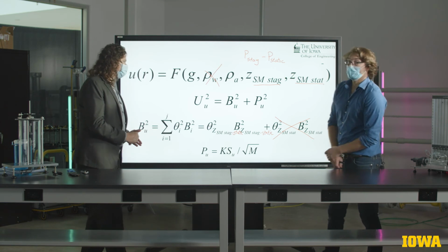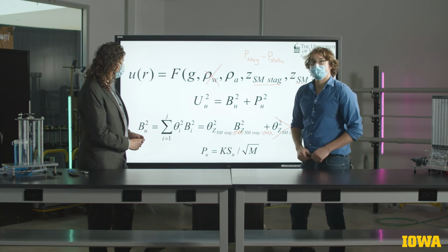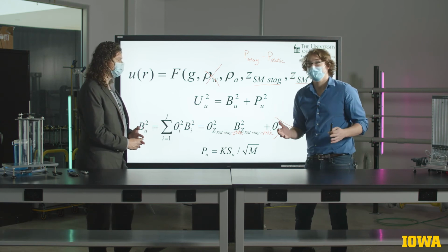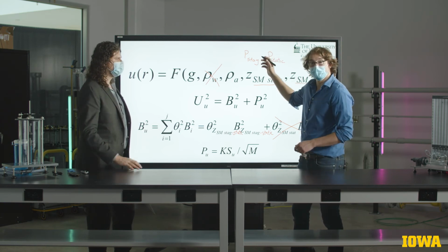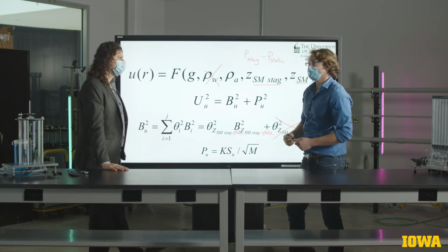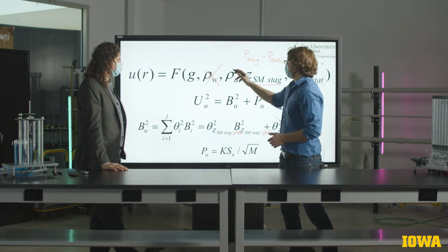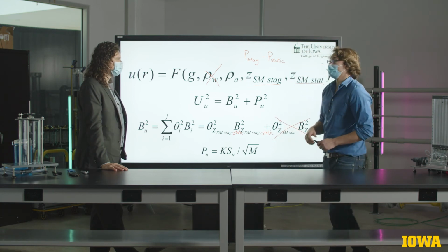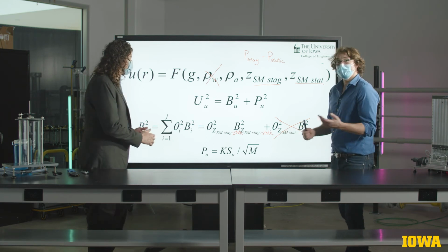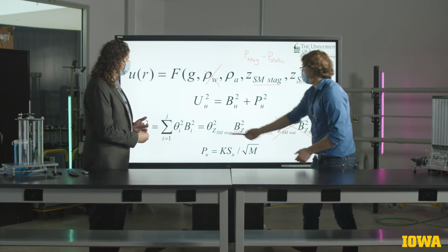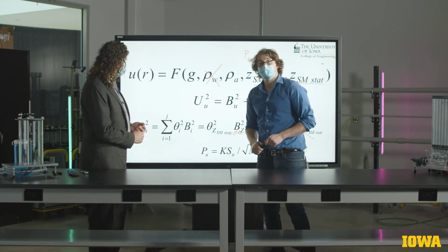That's right. So, as in the past, we're going to approach these two separately. The bias limit is going to be dictated by the measurement resolution of our instruments, meaning the pressure head indicated by our differential pressure transducers, which comes out to be about 0.01 feet, as well as the density of the air, which comes down to uncertainty in the temperature more than anything else. Once we know these elemental bias limits, we use this expression to propagate them into the uncertainty in the velocity.